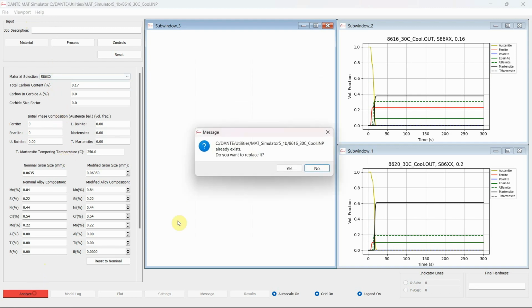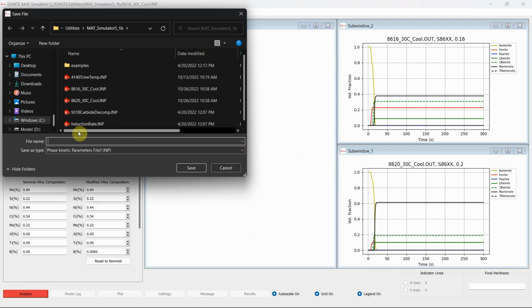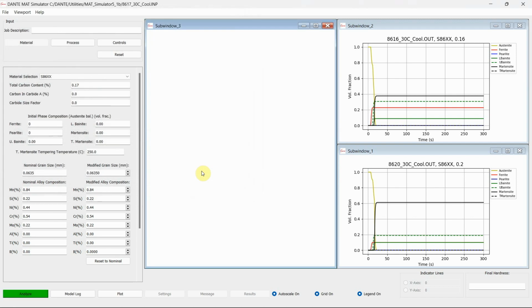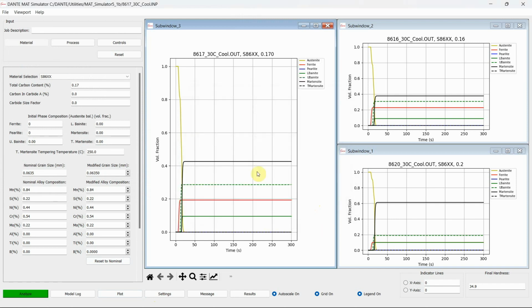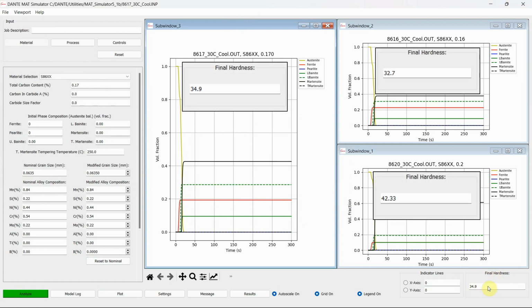You know that even on the same piece of steel, no two labs get the exact same analysis. You also know that certs represent the melt batch and there's permitted variation in product chems known as check tolerances. You send a piece to a local chem lab and you find that the recent batch was at 16 carbon, 2 points lower than on their cert, but still well within the check tolerances. Remember that when you ran the 16 carbon simulation, you got hardness predictions right where your problem parts were.